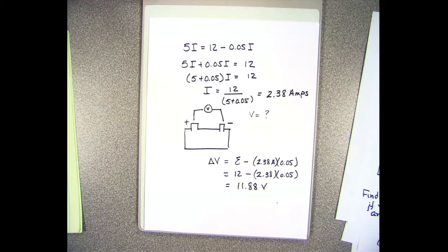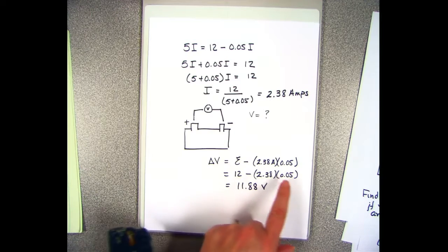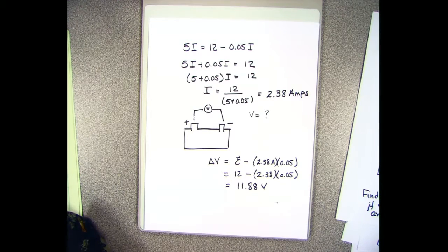And so what happens to you in the wintertime, if your car needs a certain voltage, and because of this internal resistance that's going through the system, all of a sudden I don't get the required voltage and I can't start my car. So you'll get problems that look like that.